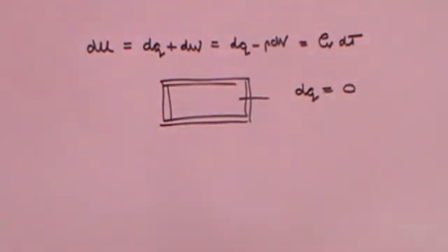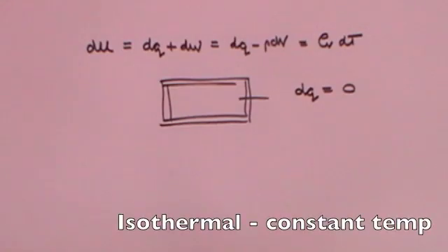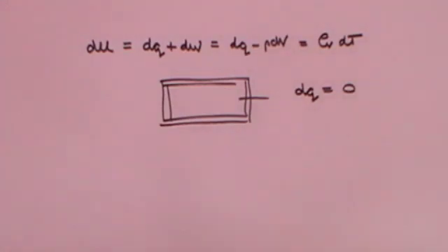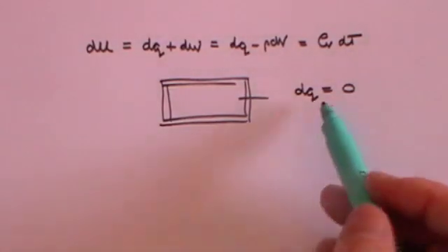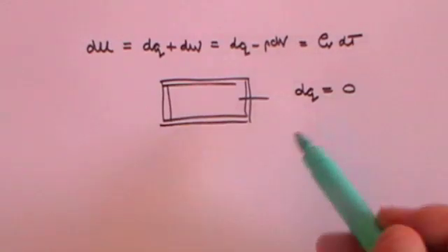And that's called adiabatic. Another type of change, which we're not looking at the moment, is called isothermal. Isothermal means the whole thing is done at constant temperature, usually at room temperature, because that's the easiest thing to maintain. And generally you have to go slowly so that all the temperatures can even out to room temperature. That's isothermal. We're going to consider adiabatic, which means no heat in, no heat out.